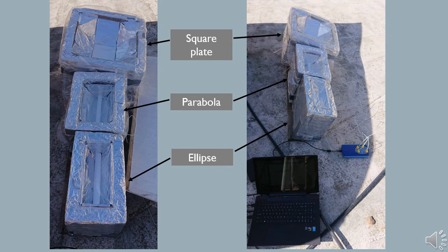Each system was insulated with a thick layer of styrofoam from each side except for the side facing up to reduce heat conduction, and covered with aluminum foil from every side to prevent heat transference via radiation, as aluminum is a very good reflector for all wavelengths. The systems were sealed from the top with a thin layer of polyethylene to reduce heat convection, due to the fact that polyethylene is mostly transparent in the wavelengths at the atmospheric window.